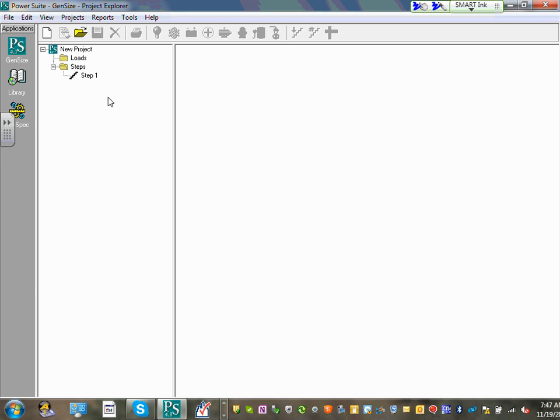All the major manufacturers of generators, Caterpillar, Cummins, Kohler, all the manufacturers, guys, have a little software like this that they give to the engineers and designers like yourself. It will help them size the generator. I don't know if you guys recall last module, residential project, when we talked about sizing a generator. You size generator current based on two things. Number one, the running load: how many kW you want to run at the same time, simultaneously. That's called the running load. Number two, how many kW you need to start from zero at the same point, at the same time. Did you guys hear me?